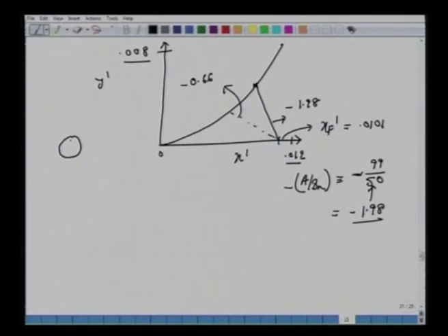So we are talking of stage 1. Bring in contact with this and this. These two are in equilibrium. So we reach here. Pure solvent is 0. Come to this stage. If you read this number, this should be 0.007. Again, from here, take the same slope because the amount A by B n remains the same. So draw a line parallel to this. So this line and this line are parallel.